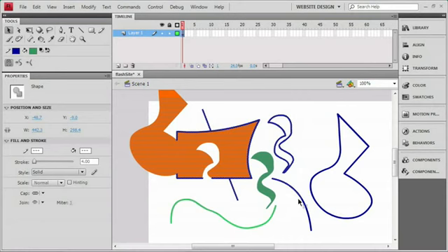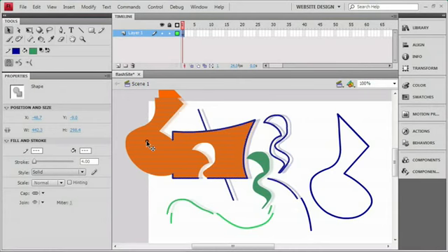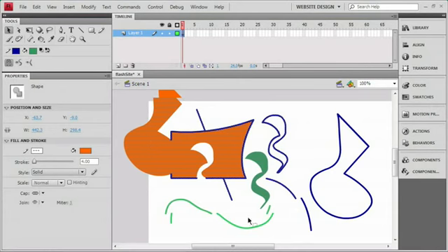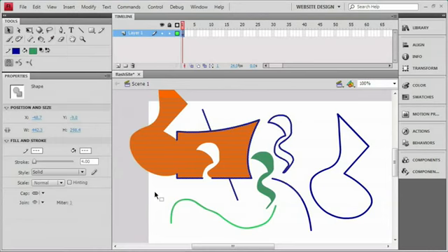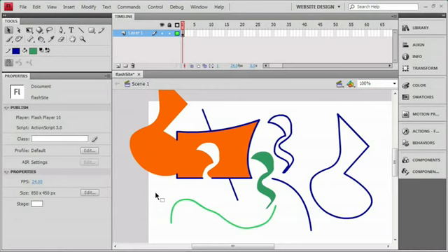Once again, we're seeing it cut apart these areas, and I'm leaving little pieces behind. And that includes the top of this fill as well. If I grab what I've selected, I'm actually going to see everything break apart at those points, and I'm going to make a big mess out of everything. So just be careful when you're using the marquee selection. Now I'm just going to undo that change so I don't leave these pieces all over the place, and I'll click and deselect.